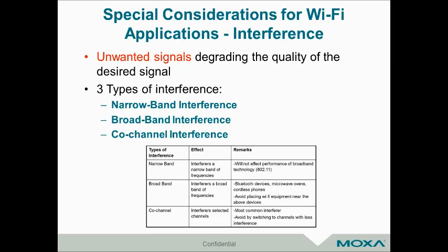If you're going to go 10 kilometers and under, which is still a pretty good distance, typically all you're going to have to do is some parameter adjustments within your communication devices, and some of them will of course have support for that built in. You'll also need some of those high gain antennas. If you want to go farther, so 10 to 20 kilometers, you're going to need a little bit more specialized equipment. That includes either a higher powered radio module or some kind of booster or power amplifier to bump up that signal to travel that distance. And of course you're still going to need those high gain antennas. So that's a trickier solution, but it is possible with Wi-Fi nowadays.